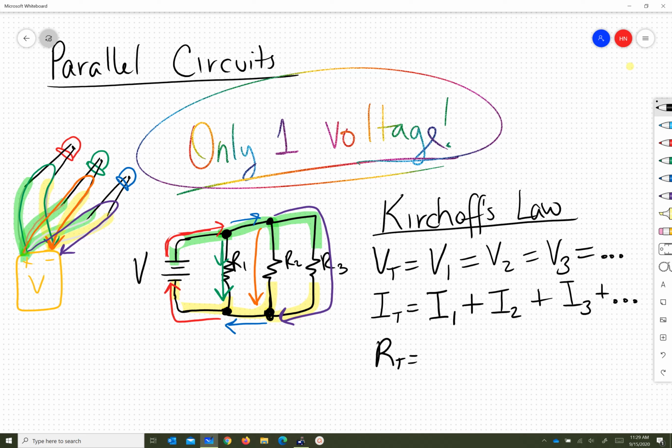No matter what, the fact that you have another option, another pathway, tells us that if the resistance of the pizza is 100 and the resistance of the salad is 200, the overall resistance is going to be less than 100, because having the salad line is going to help no matter what. So the result is always that the total resistance in a circuit is less than the smallest one.